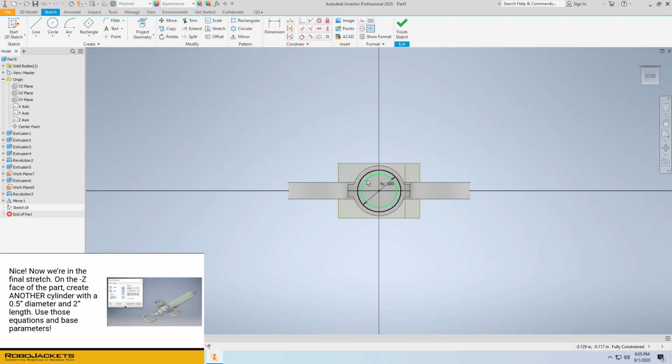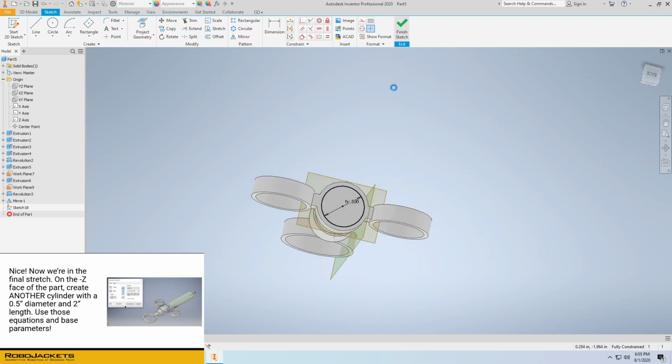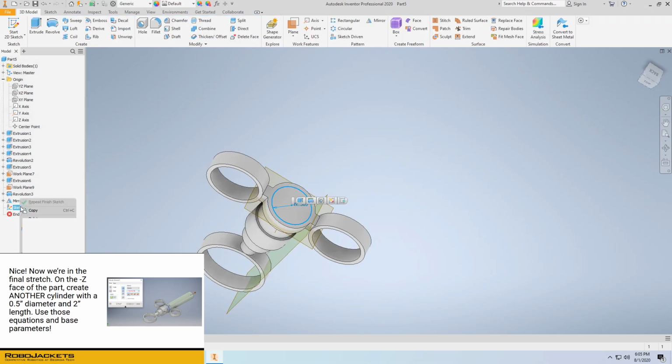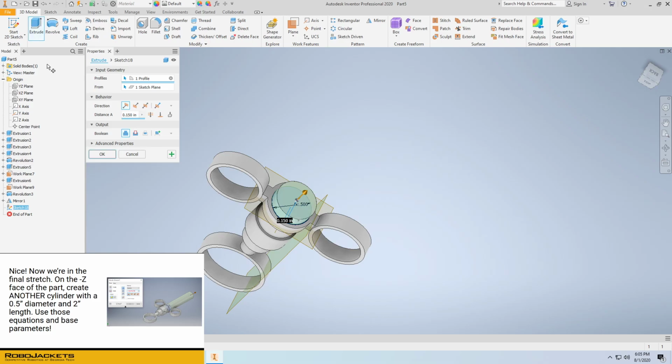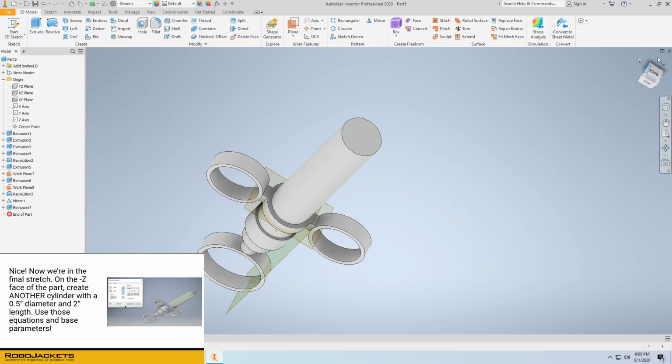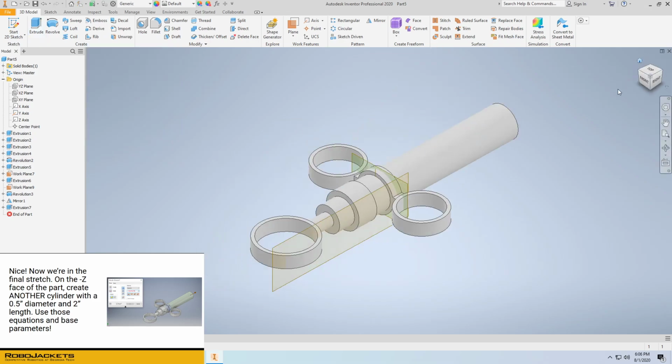That's a projected geometry. Go ahead and extrude our sketch 2 inches. Now if you remember, our main thickness was 0.25, and so that's going to be an 8 times scale. There we go. And headed back to home view. We can see that it looks just about right.